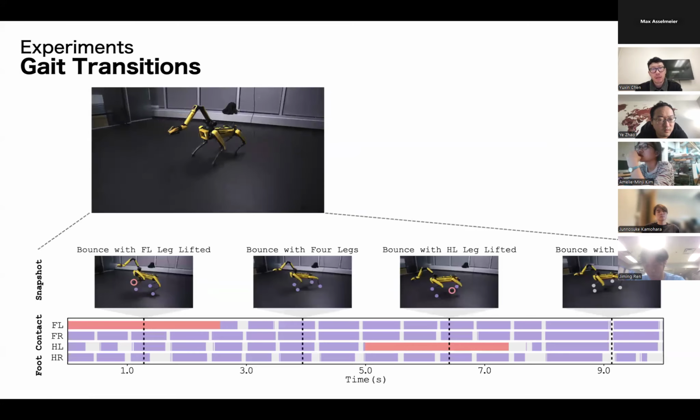And here we show a demo without the gait regulations. This purely emerged from the reinforcement learning. If we don't have additional constraints in the reinforcement learning training, it will produce some weird, undesired behaviors, because it just tries to jump with all 4 legs. You can see it's just bouncing up and down, so the tracking error is very large.